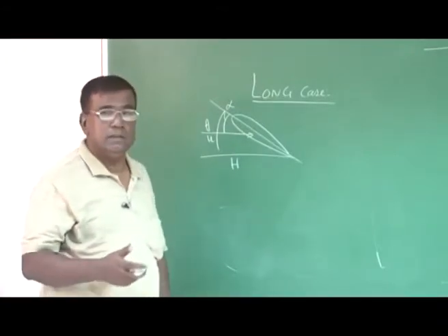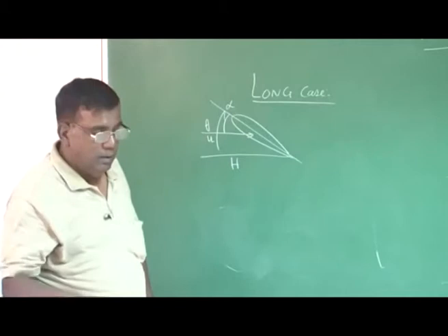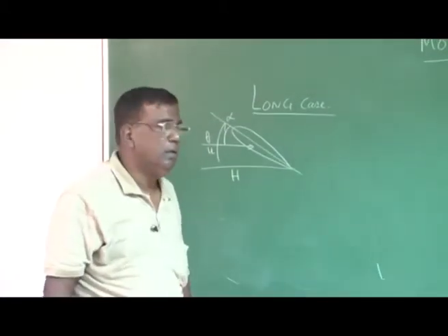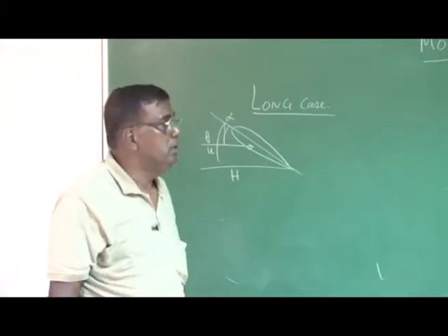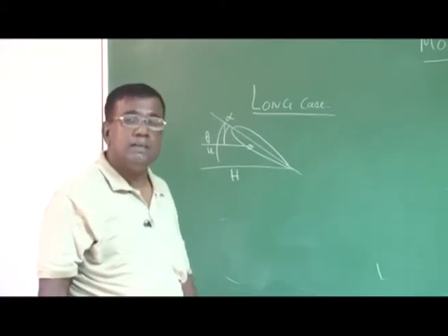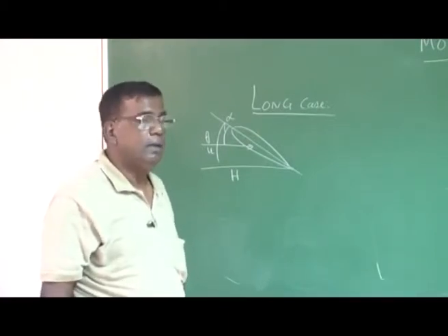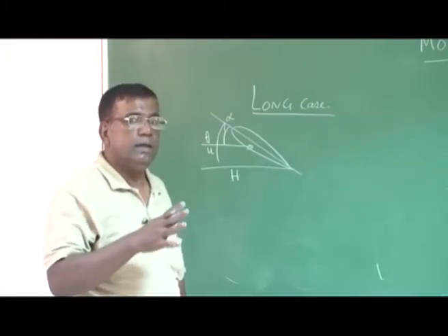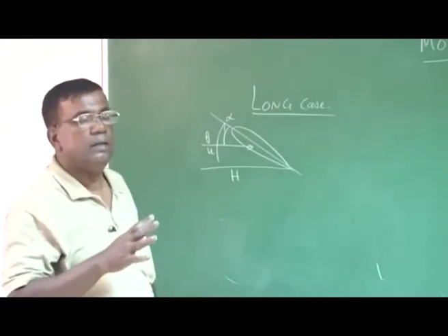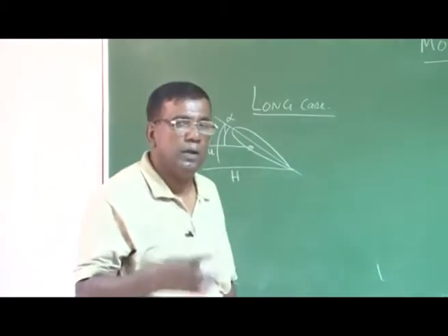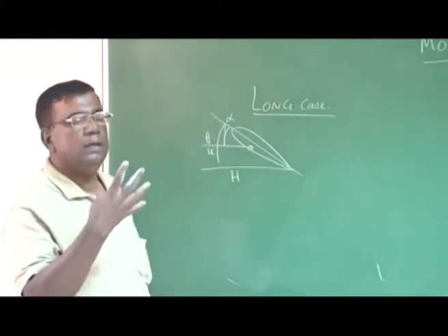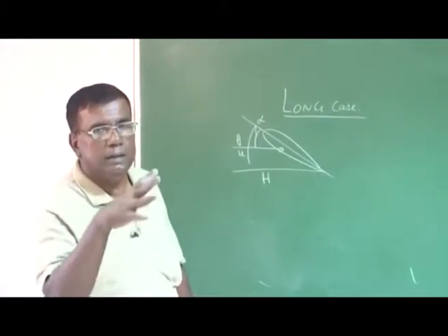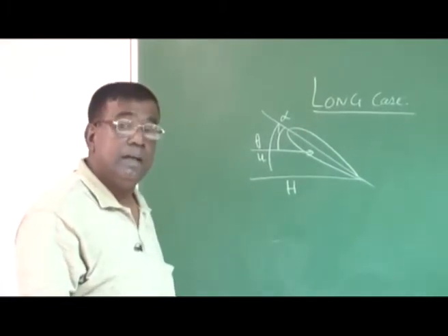We are talking about linear system, right? Now control has gone much beyond using linear approach or using transfer function approach. We will talk about state space modeling, so many things, but a good control designer knows he has to be very clear about the transfer function approach. A lot of information you get, okay? You could see physically, close your eyes, you could see, oh, this is happening, alpha is increasing, theta is increasing, what is the magnitude, what is the phase difference.